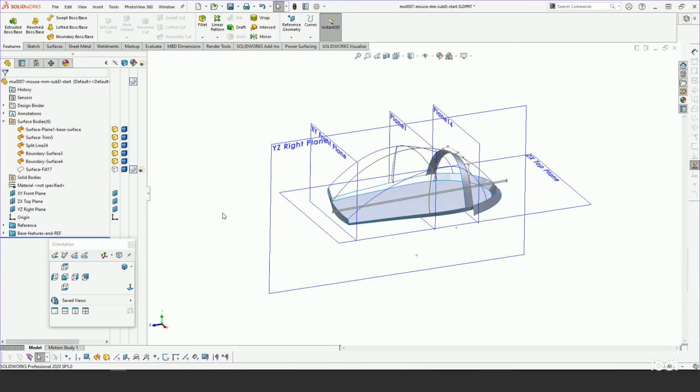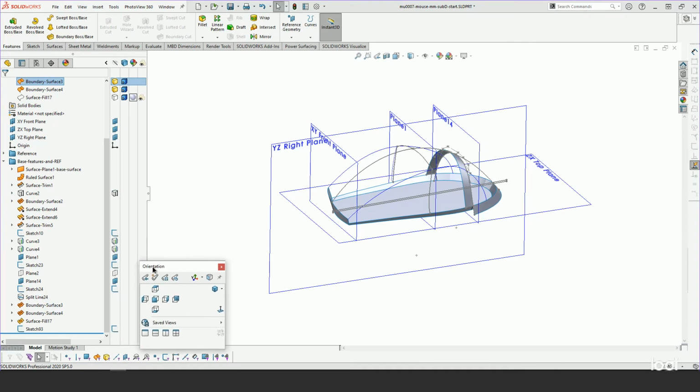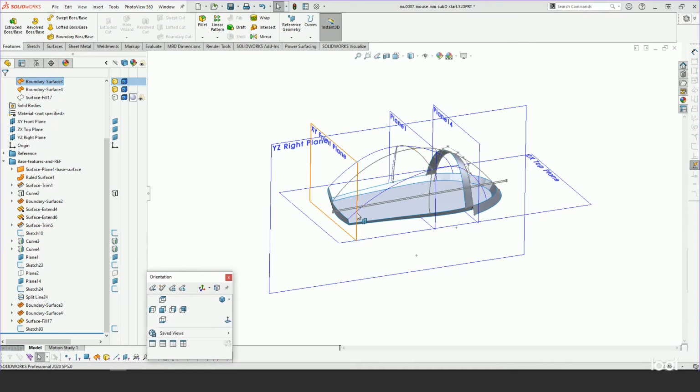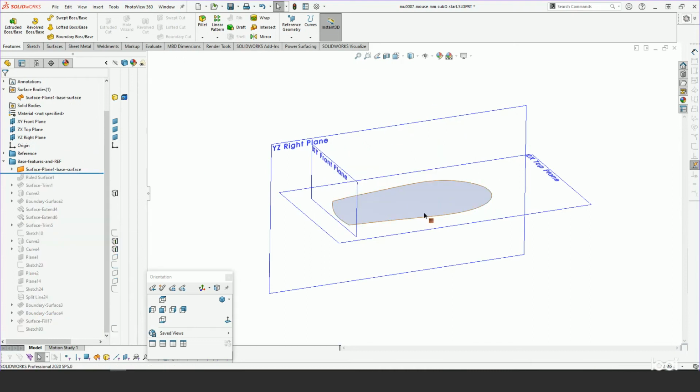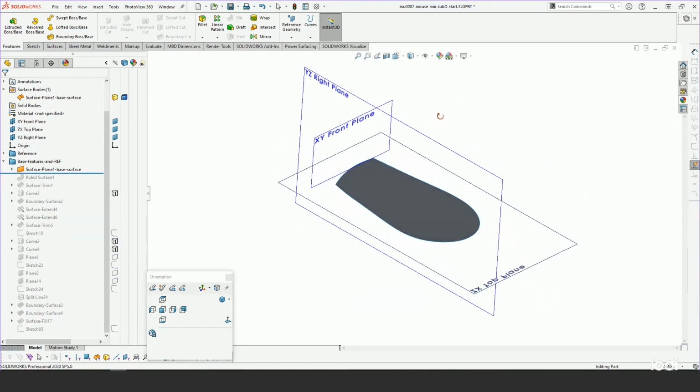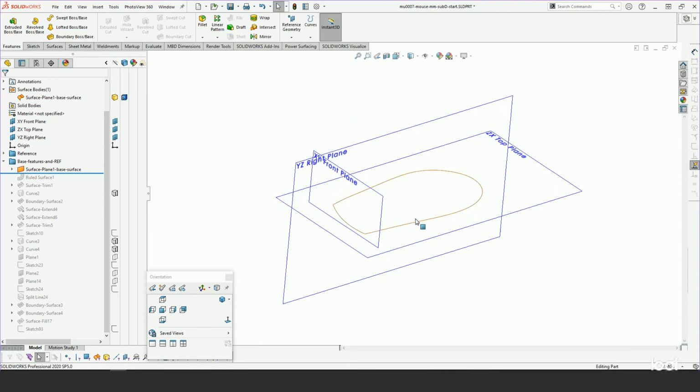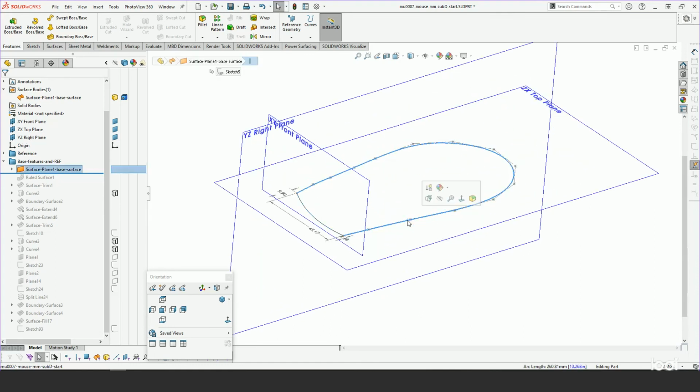and then just move to the next part of this exercise, and that is to create some base geometry that is both reference and is actually used in this mouse. So probably the base feature would be the actual base, which is this profile. So if we roll back to that, we're just creating a planar surface that defines the bottom of the mouse and is created out of a single through point spline, or probably a style spline. And that becomes the basis for the entire design.